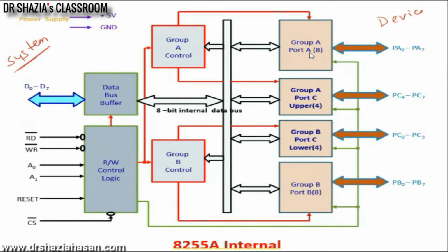We have discussed previously that a port has two parts. One is the size or type of the port, whether it is able to transfer 8-bit or 16-bit data, and the other is the address of that particular port. Whenever we write an IN and OUT instruction, we have two parts: one defines the port address, the other defines the port size. Size means the size of data it is able to transfer.